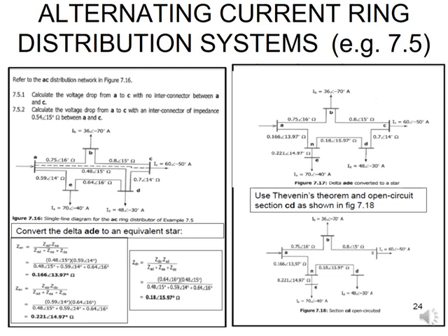So now we're going to start utilizing all the different ways of calculating with that open circuit open. Just looking at the diagram before you go to the first page, you can see, looking at the top part, that your IBC is obviously going to be equal to your IC, and then your IAB is going to be equal to your IB plus your IBC. Then looking at the bottom part, you see here that your ID is going to be the same as your IDN, and then your IAN is going to be the same as your IE plus your IDN.